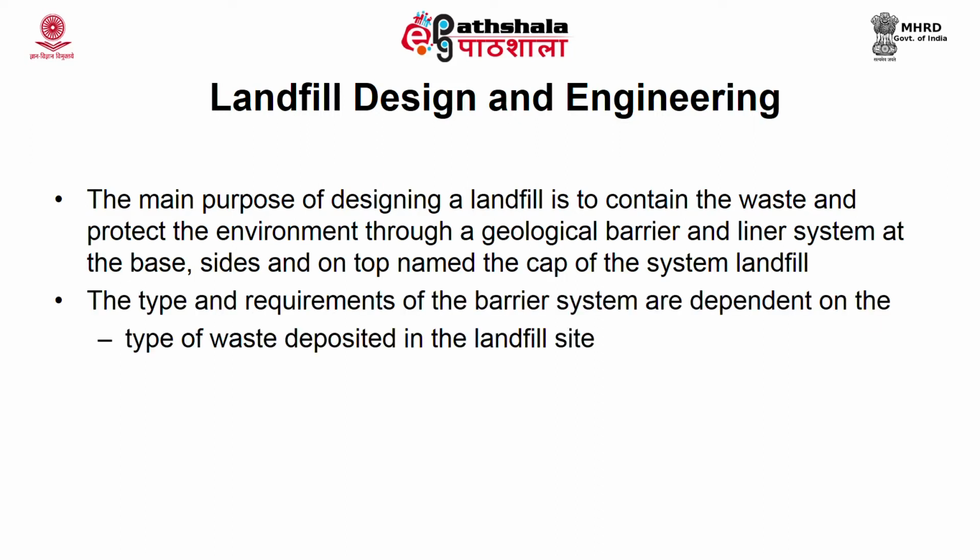The type and requirement of a barrier system is always dependent on the type of waste that is to be deposited in a landfill site. That is, it can vary according to the nature of waste. For hazardous waste you have to have a more secure liner system when compared to municipal waste, and inert waste does not require a very efficient liner system because it is non-biodegradable. It is not going to contaminate or affect the environment to a larger extent.